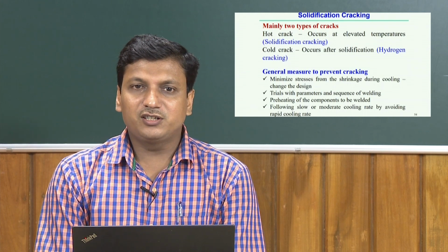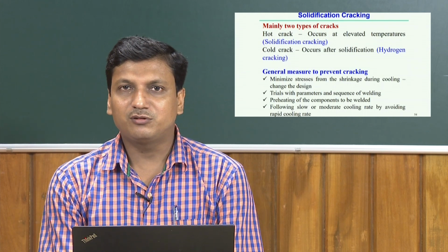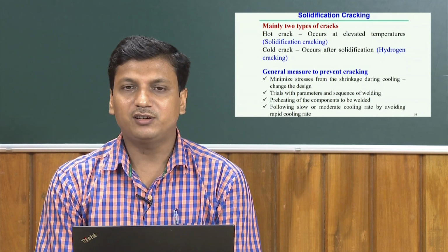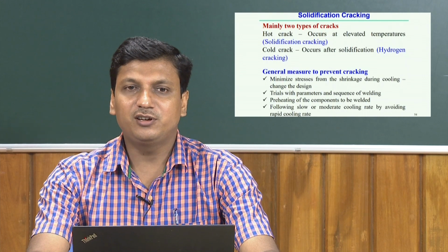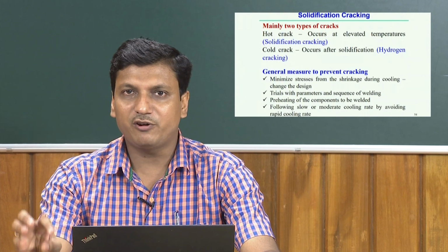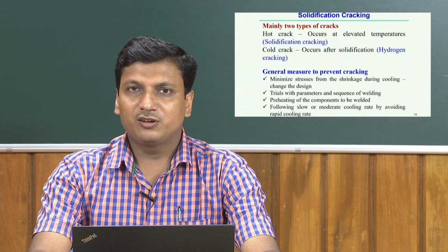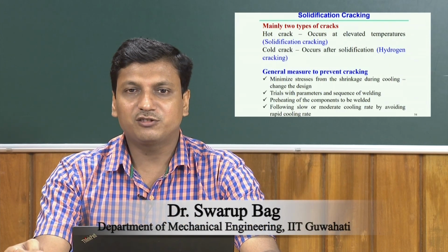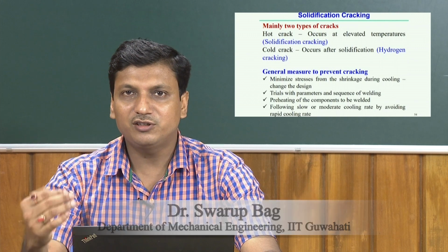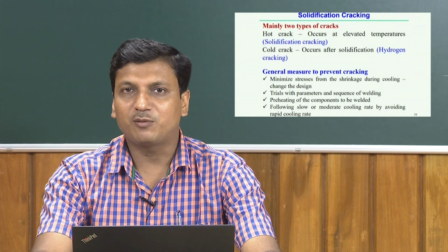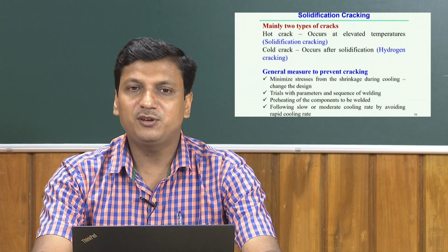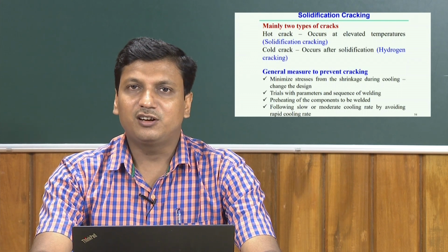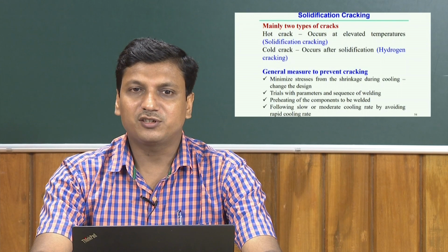But what are the general measures necessary to prevent the cracking phenomena in the welding process? If we look into that, first always try to minimize the stresses from the shrinkage during the cooling period. To do that, it may depend on a change in the design during the solidification process.